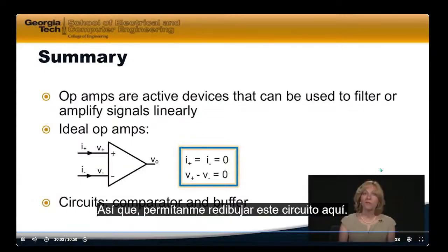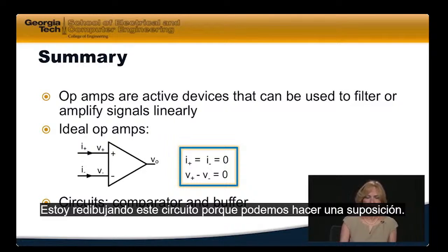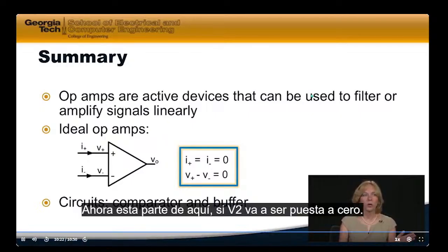So in summary, we've defined a gain, which is the multiplier of the input voltage to give us the output voltage. We went through some basic circuit configurations: the non-inverting and inverting amplifiers, and the difference and summing amplifiers. These are really, really common and very useful circuits, and we use them a lot of times when we're